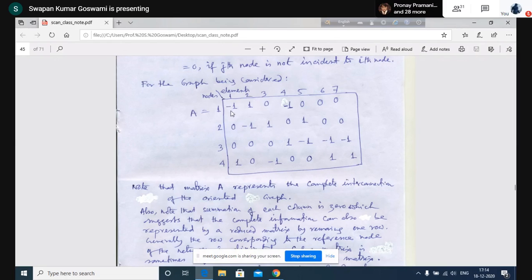Now you multiply this matrix, the branch to branch admittance matrix, which is a diagonal matrix as I mentioned earlier, and the transpose of this matrix. You see that you are getting a matrix which has only admittances at the different positions. There will be the self elements of the matrix, and you will have admittances in the mutual elements also. That means diagonal terms will be admittances, mutual elements also will be admittances, and you will be able to identify that matrix as the nodal admittance matrix of the network.